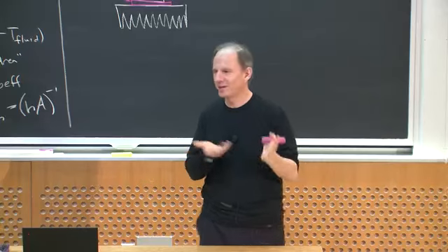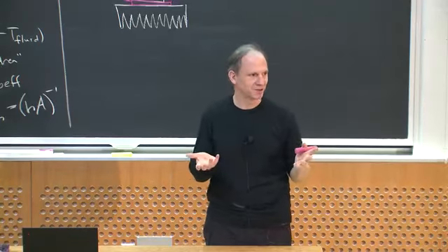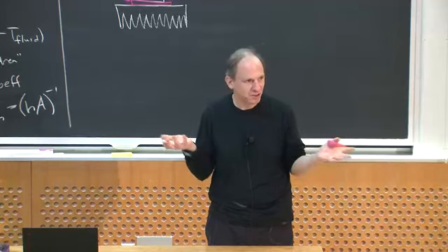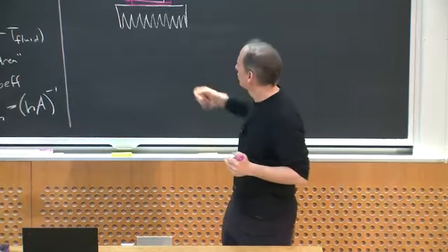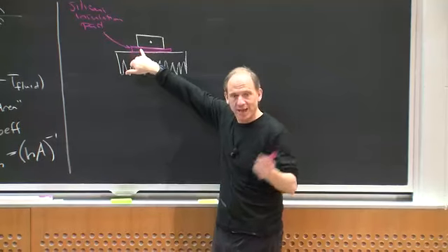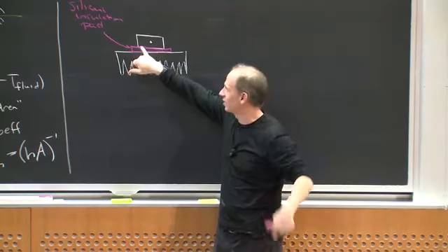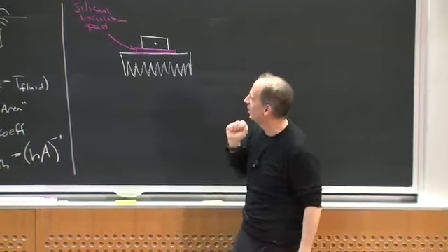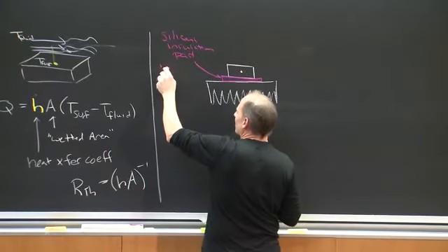And by the way, that's not a very common thing, right? Most things that are good thermal conductors are also good electrical conductors. But you can find some materials that'll help you out there. So this thing might be some electrical insulation pad to let you connect this thing to a heat sink thermally, but not electrically. A typical brand name for this is like a Sil-Pad.